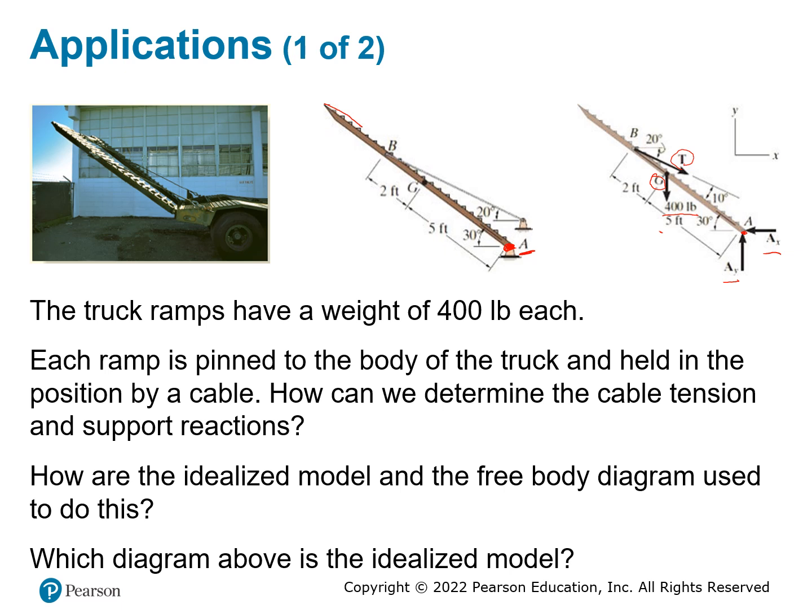If you don't consider these forces, it will never be balanced, because this tension has a rightward and upward component, and this one is going in the negative y direction. That means if we don't have a force in the negative x direction, this will never balance. And that's why you have this reaction force here to balance it.